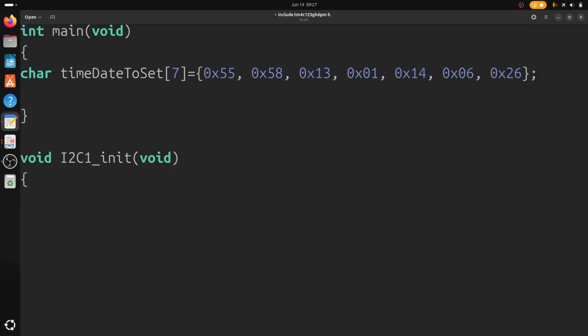System control is using I2C GPIO equal to 0x. Let's choose GPIO A. This system control register is choosing this particular register, RCGC GPIO, that 32-bit register.